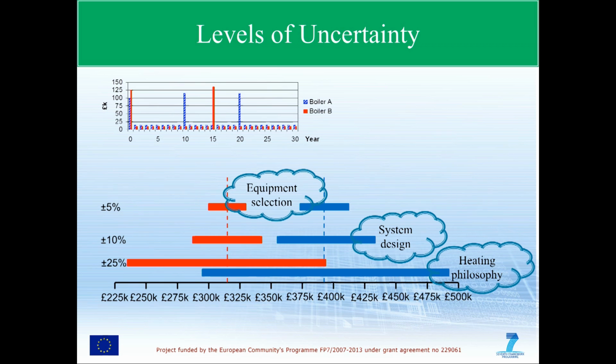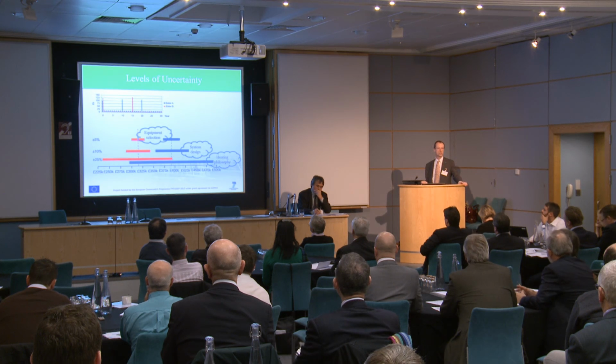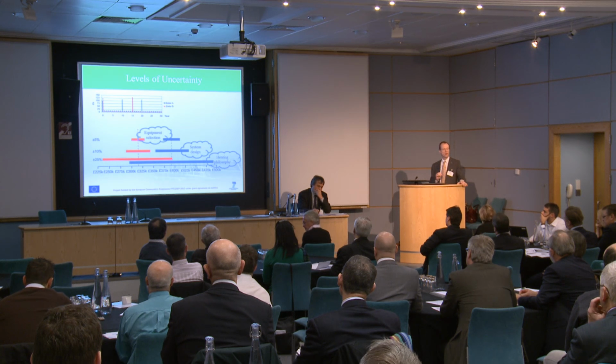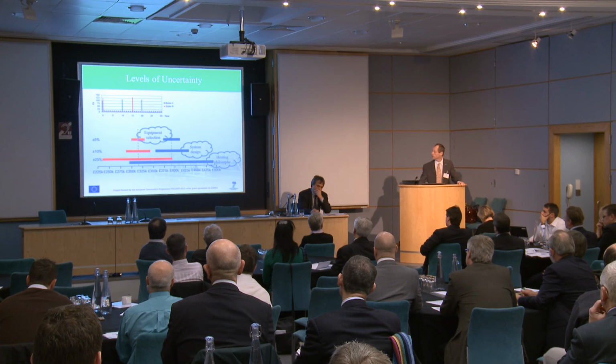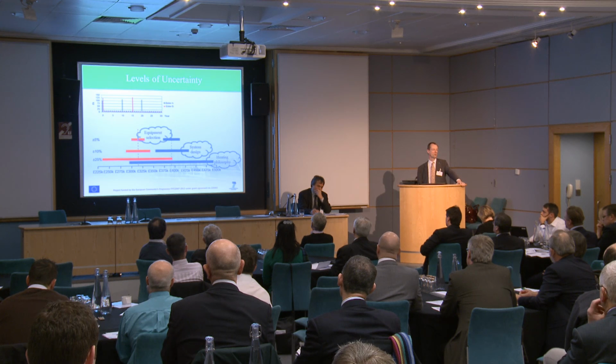But if I'm at a period of the design process where I really don't know very much about the scheme, I might just be thinking about the philosophy of heating. So I won't actually know which particular model of boiler I'm going to choose, or I may just have an idea of what type of system it's going to be. The design is going to be very uncertain, not very fixed, and so there's likely to be a plus or minus 25% health warning on the life cycle costs that you calculate.